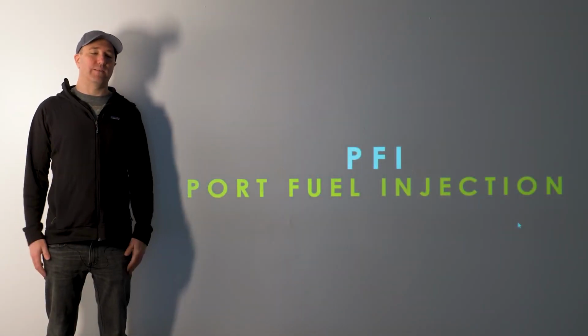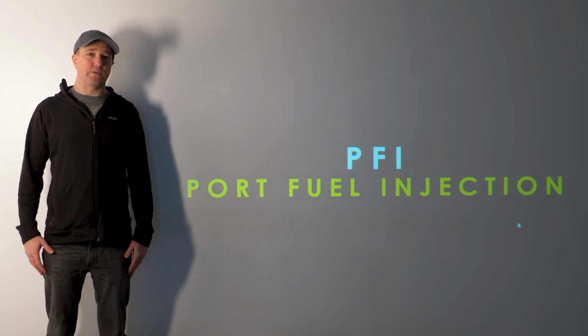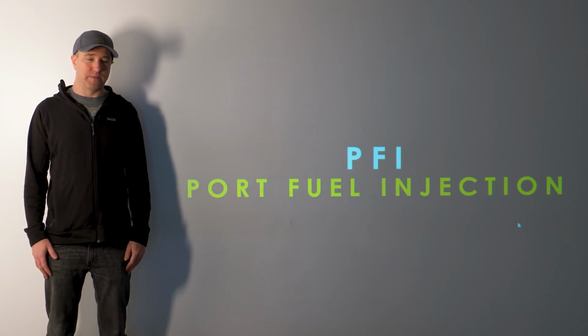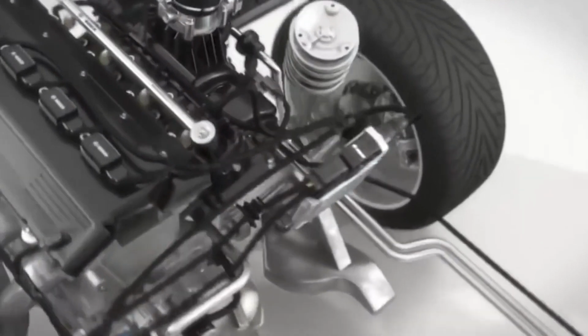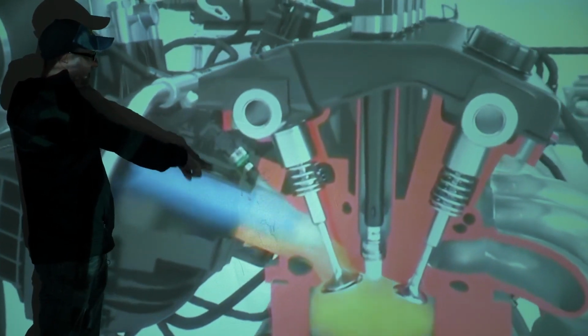Now, there are different ways to deliver fuel electronically. Before direct injection, what the mainstream is right now, still with most cars on the road, is PFI, or port fuel injection. So let's take a look at how port injection works versus direct injection. Port injection, much like direct injection, you fill up your tank, there's a fuel pump that sends fuel through the fuel lines to the front of the car, assuming your engine's there, directly to a fuel rail, and the fuel rail will distribute fuel to the port injectors, which then spray into the cylinder head.